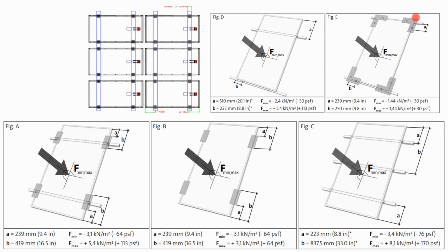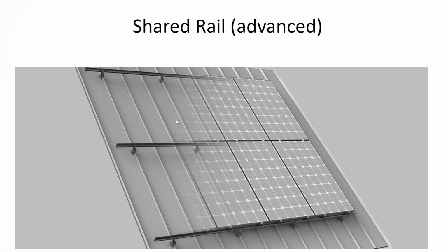Likewise, mounting to the corners of the panel may enable a landscape mount, whereas otherwise you might be mounting in a portrait mount. Generally, panels can be mounted in both portrait and landscape, but it never hurts to check first because it is a competitive market, and panels that have less framing built into them have less inherent strength and may not be able to support all kinds of mounting configurations.